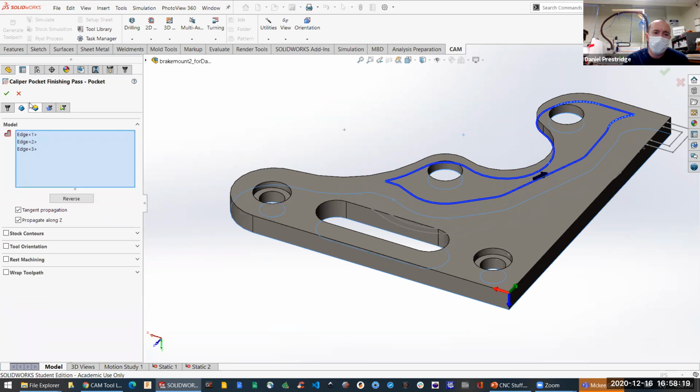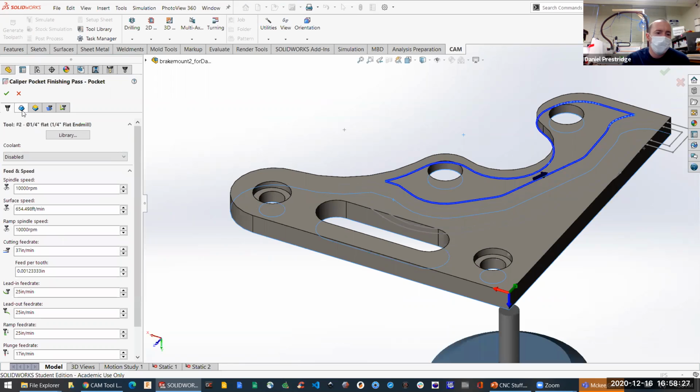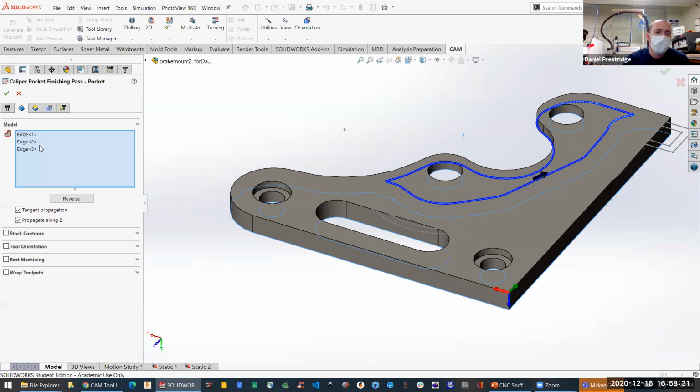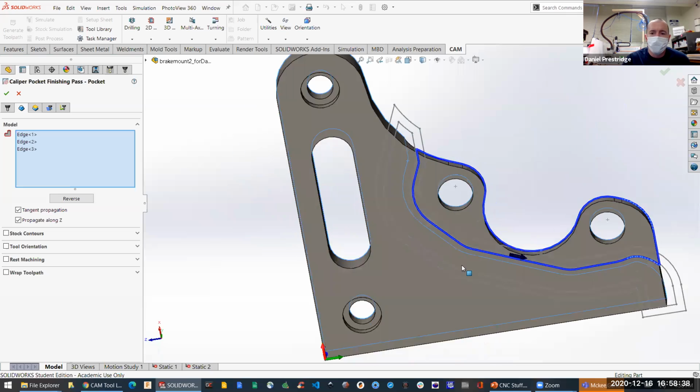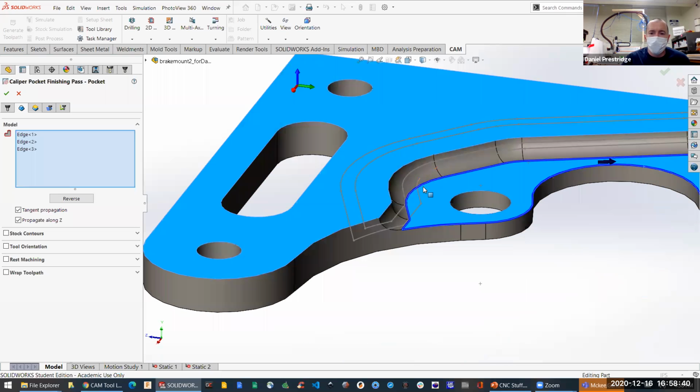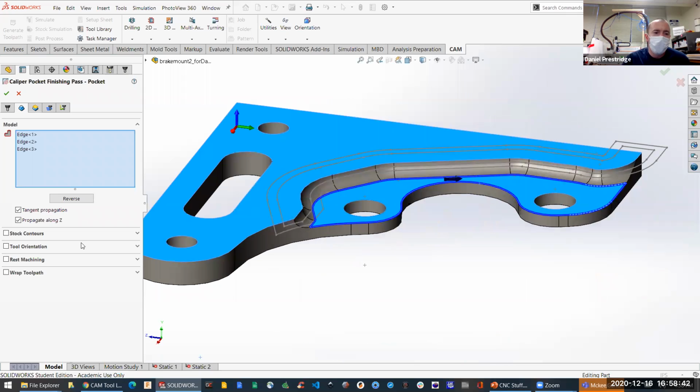And that's one of my favorite things about the Autodesk environment: each one of the tabs is sort of like, okay, the first one is speeds and feeds. What tool is it? How fast are we going to move? The next one is, okay, what am I actually cutting? Is it this right here? It turns out to be this right here, but what area of interest do I have? And then it has some extra material.